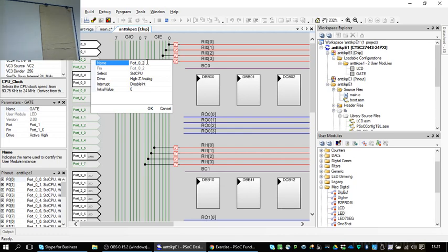You need also, oops, not short circuit, but you need a DC way to ground, right? That will be just a legitimate connection. However, you can always use the internal pull down resistor. Okay, in this case, you wouldn't need the external. And you would do it like this. So yeah, port 0.2 would be called button.